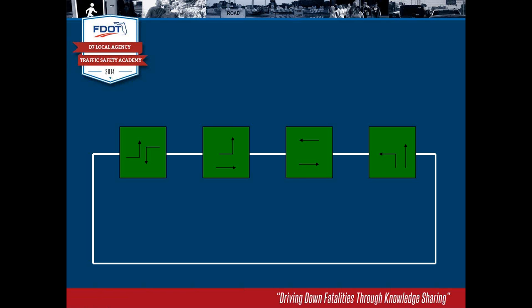Now we said we had no southbound demand at all, but we had some for the lefts and some for the throughs. So the northbound left turn and through will come on together, satisfy the demand, and then we start it over again with the next cycle. The next cycle might have completely different conditions. So this is what happens on one cycle at this fully actuated intersection.